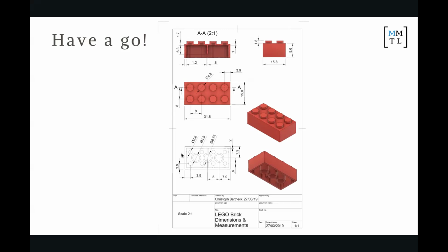And then from there, I created the cylinder on the top. And then used a pattern to create the rest of the 8. And then because they all had a cut inside each of them, I then created a circle underneath it. And then again, used the same pattern to get all 8 of those. And the next part I did was I just created the cylinder and then extruded that out. And then again, a pattern for that as well.